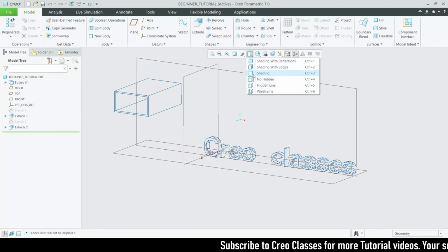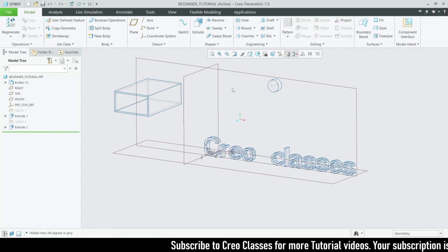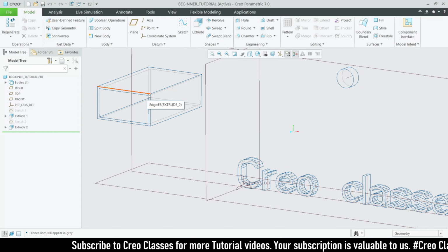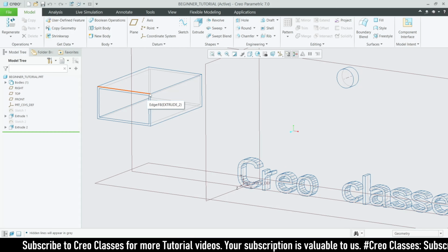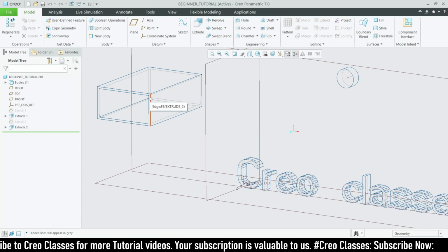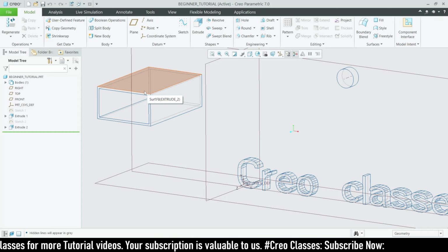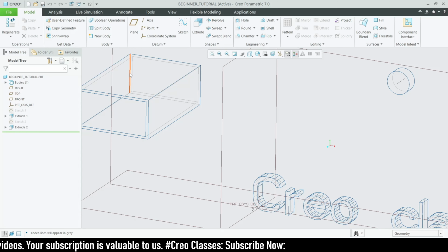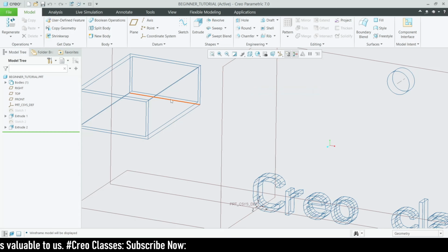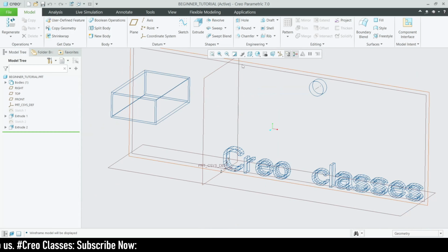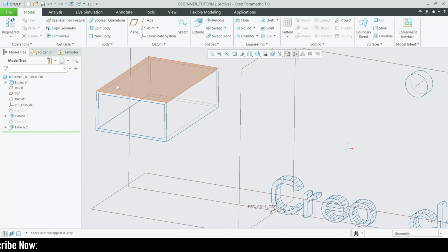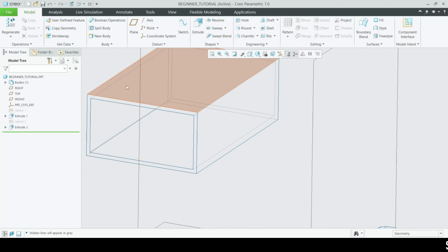If you go for the hidden line feature, you can see it like a 3D sketch. While studying, we will draw some 3D drawings like 3D cubes, and we will draw the back lines also. As you can see, we are able to see the back lines. This is called hidden line. Wireframe is similar to hidden line, but with the hidden line option, the back lines have a low weight.